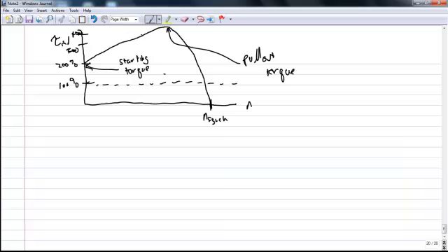For a given slip, the torque rises as the square of the applied voltage, and we can use this idea to do some speed control. If the motor is driven faster than the synchronous speed, the induced torque reverses, and then the machine becomes a generator. Finally, if the motor is turning backwards relative to the direction of the magnetic fields, the induced torque will stop the machine rapidly. And so switching any two stator phases could be used to quickly stop an induction motor. So those are some things that we can observe by looking at this graph and the equations.